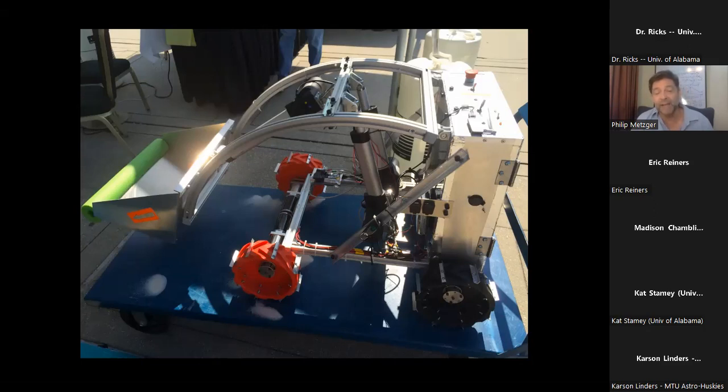But if you didn't design at least 100% safety margin in your mobility system to go from four wheels down to two, meaning four wheels has double the amount of traction that it needs, if you didn't design to that much margin, then once you've got wheel diagonalization, you're stuck. You can't get out. And so we saw this happen over and over and over. We were amazed, why does this happen? Well, I just gave you the explanation why. It took us a few years to figure that out.